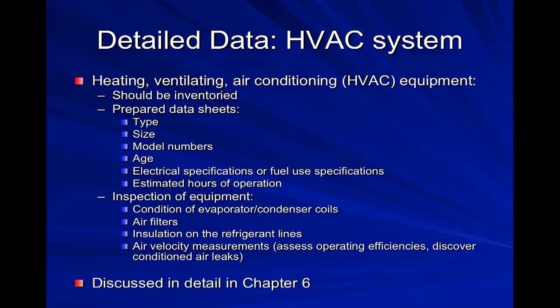This information that's listed here is going to be required for almost every piece of equipment that we talk about here. We need to know what it is, what size, any sort of model numbers, any sort of age, how long has this been operating, what kind of fuel does it operate on, could it be operated on a different kind of fuel. We have to look at the condition of it. Has it been adequately maintained? Does it require a lot of maintenance? It could be that things that are old and inefficient might be prime suspects or prime opportunities for being replaced with newer, more efficient, more reliable equipment.